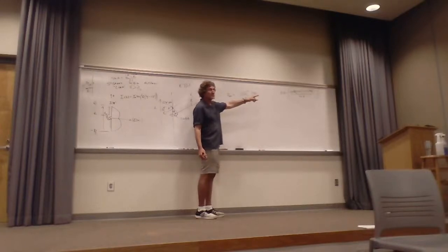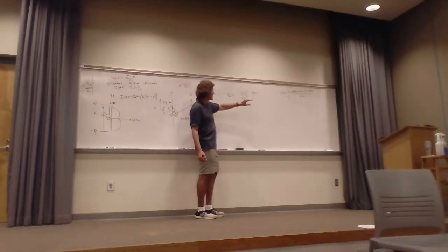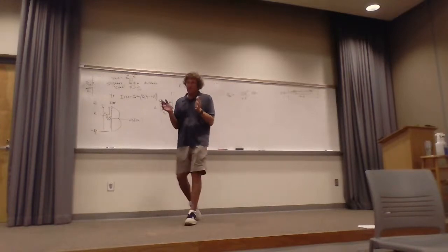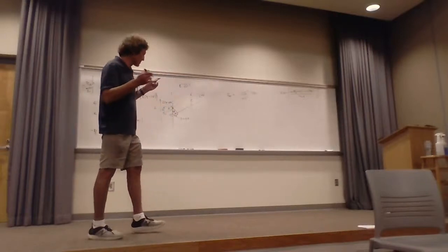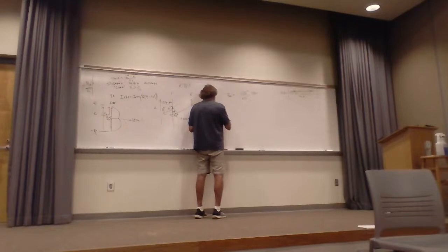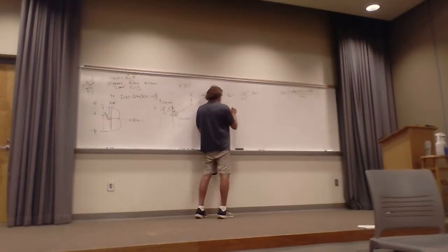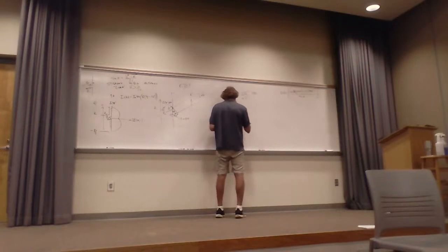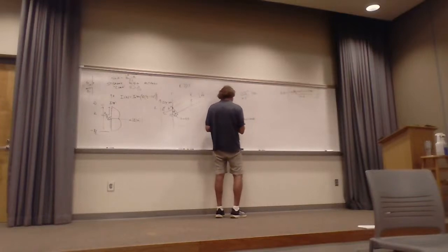The gain calculations are where it gets a little problematic, because if this is the power density, and I want the value normalized so the maximum possible value is 1, then for the directivity calculation, D max, what I need is 4 pi over the double integral of the normalized power density times the sine of theta d theta d phi. Theta goes from 0 to pi, and phi from 0 to 2 pi.